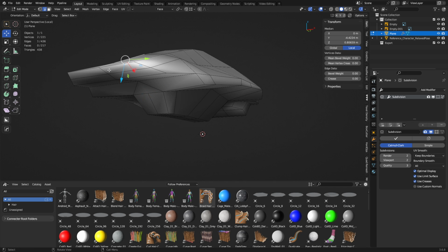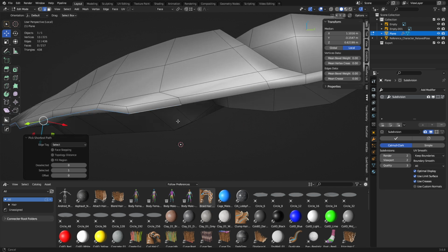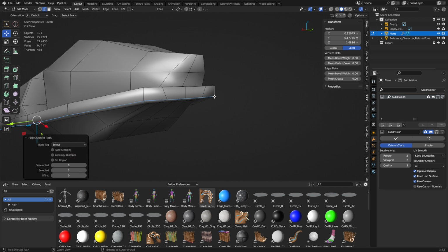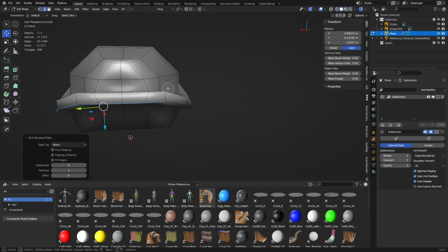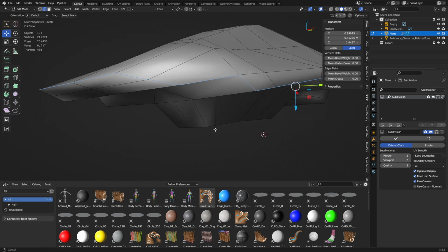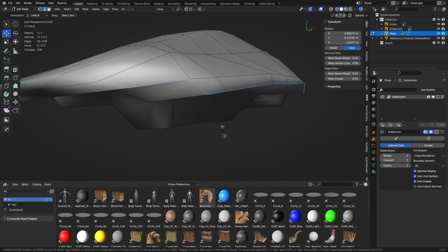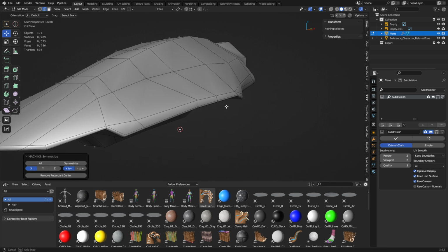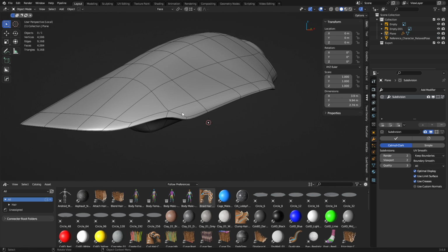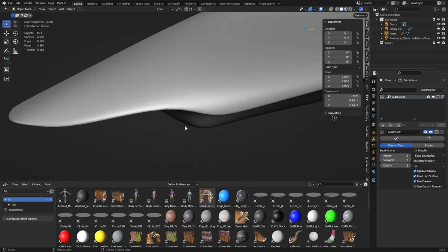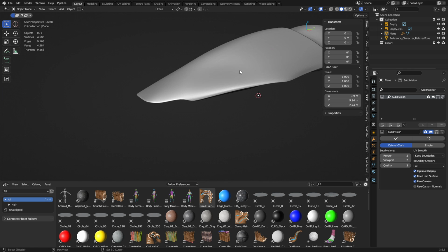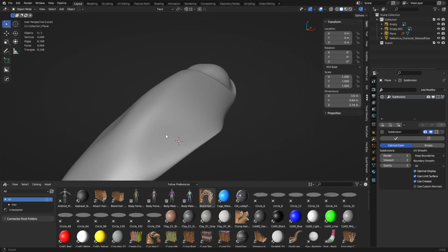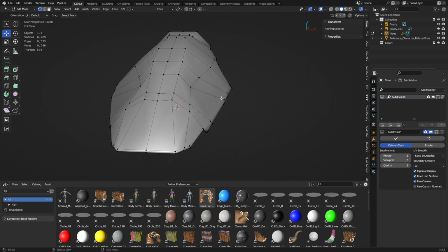And even something like this edge here, if we want to shift that pole, we could work this entire edge all the way down to the other side and cross the symmetry. So if we bevel this later on, mouse wheel up once perhaps, you'll see it shifts that pole up. So we're symmetrized now. Look, we don't have such a strange shading issue here, or a subdivision issue anyways. But yeah, this is a process you go through, guys. You can do this all day long.